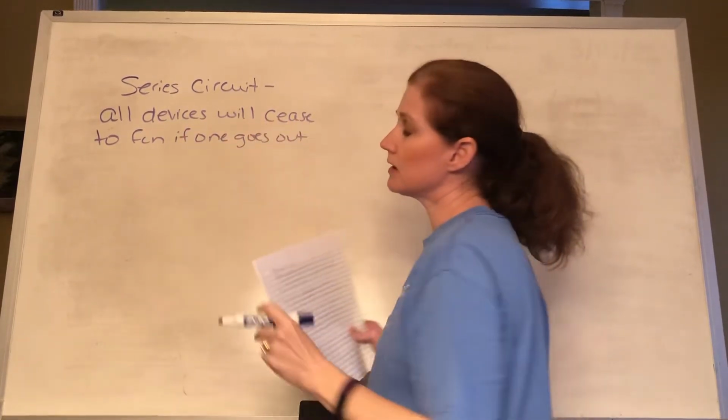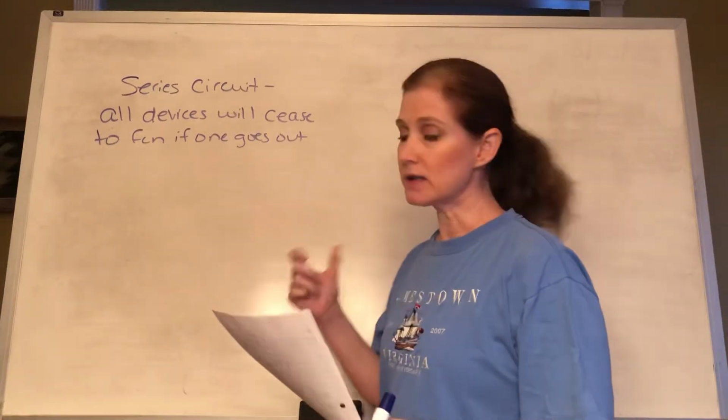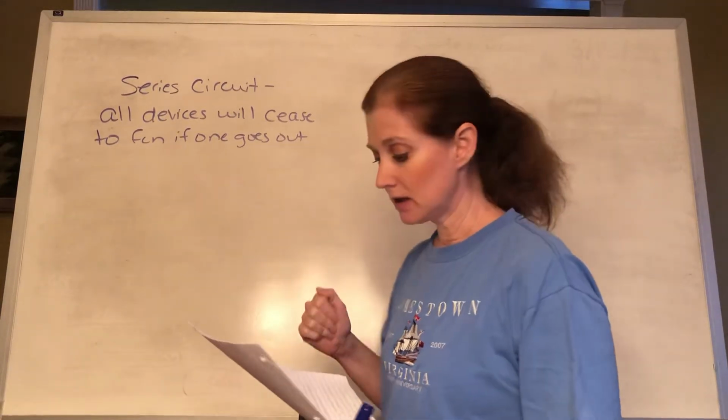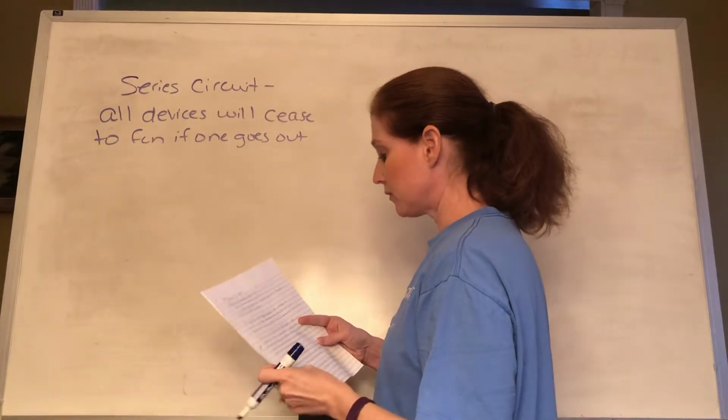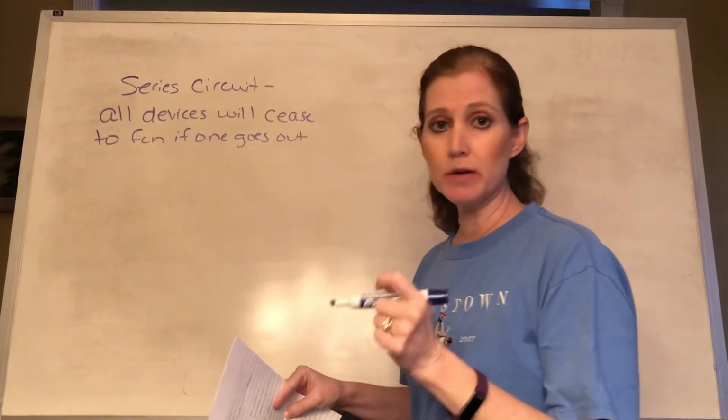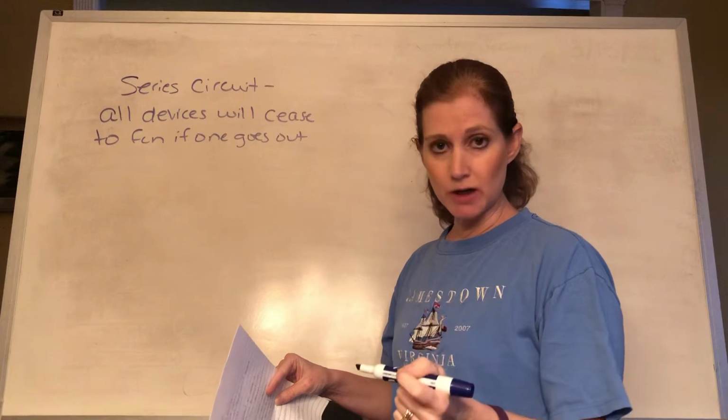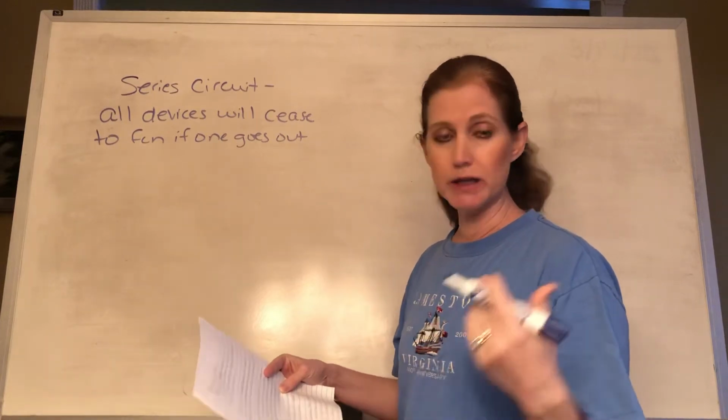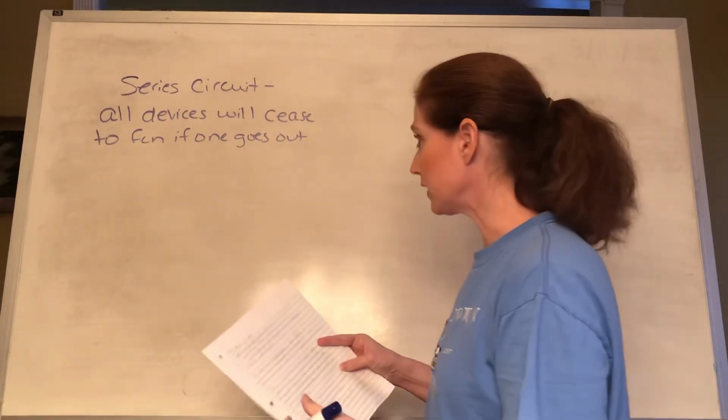Okay, so series circuit, all devices will cease to function if one goes out. Because what happens is that when that one goes out, it breaks the circuit, and so it's an open circuit, and the current cannot flow.